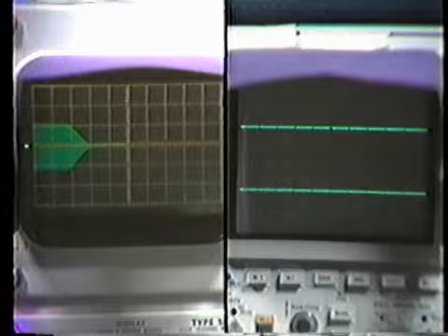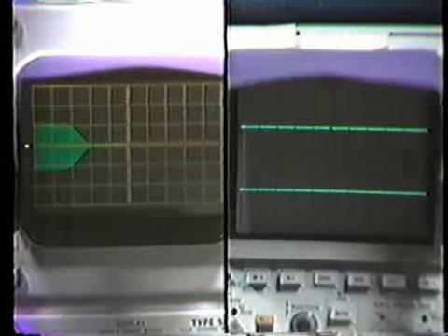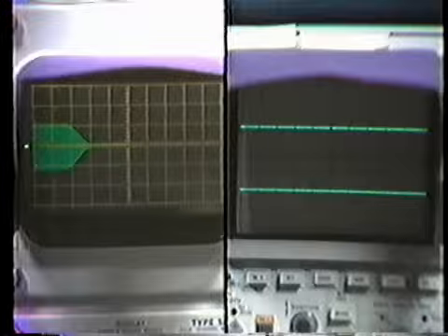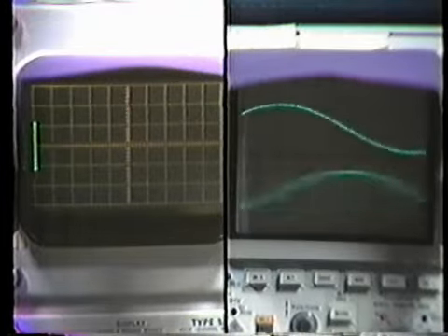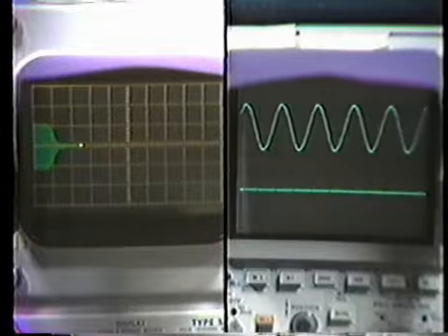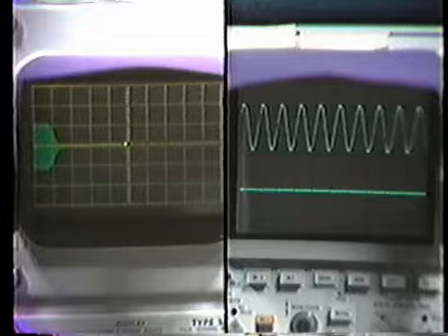Now let's begin to decrease the filter sampling frequency. So from 40, let's change the sampling frequency to 20 kilohertz. We should see the cutoff frequency cut in half. Now we can go even further.